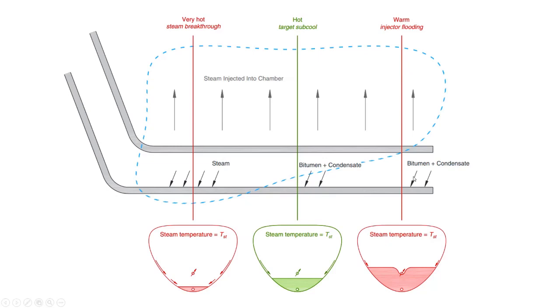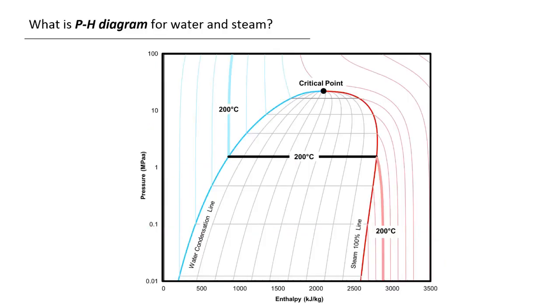If you put in large subcools, that means the liquid pool height is growing towards the injector, and you have cases where you inject the steam into the liquid pool and you get shocking effects. They call it injector flooding. On the lower end of the spectrum, the subcool is pretty low. Flashing starts close to the producer, or the producer goes above the height of the liquid pool and is exposed to steam, and you get huge steam coming in. Steam coming in means pump failure, scaling, and a lot of other concerns. That's the case you don't want to happen in SAGD operation.